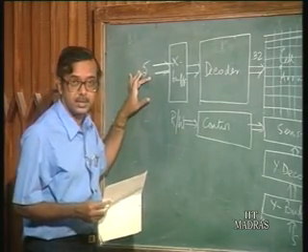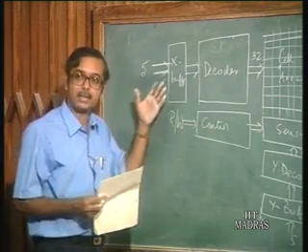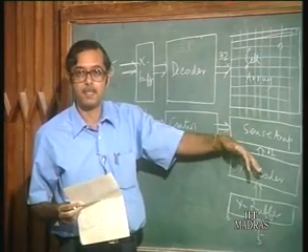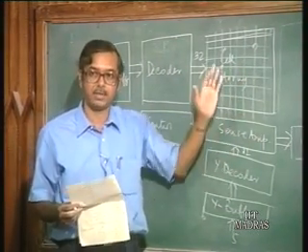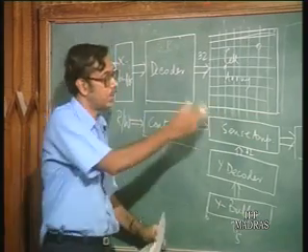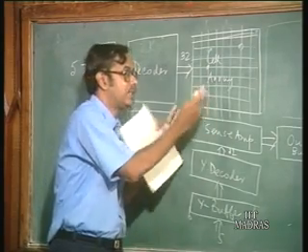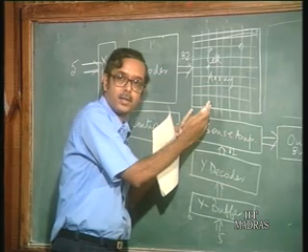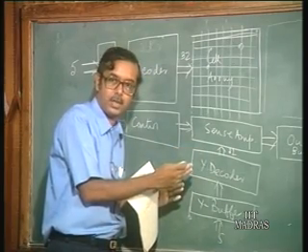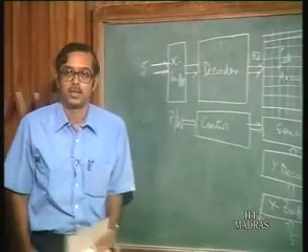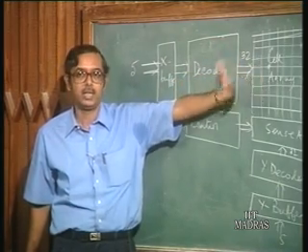Okay. So what you do is, instead of 5 address lines, you can have 7 address lines here, all right. That means you have 2 to the power 7 rows, and so you will also have 2 to the power 7 columns, okay, basically giving you 16k cells. Then you again have to multiplex or choose, so you get for each block of 16 columns a 16-bit information, all right. So that way you can make a square array. So if you know how to make a 1-bit memory, you can reproduce it generally to make a 16-bit memory.